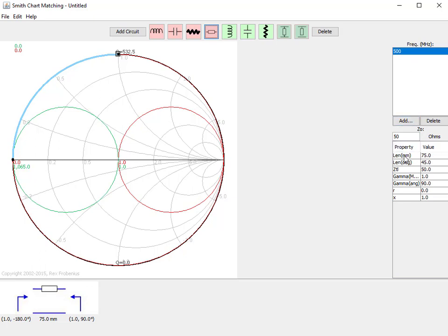So the physical length of the line can be calculated using the formulas for electrical length based on frequency. And it's also going to depend on the wavelength and the dielectric constant, because the dielectric constant has the effect of shortening a wavelength in a line. So this is all for a transmission line that has a dielectric constant of 1, or the same as air.